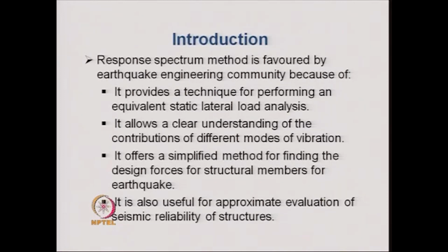In the design stage, it is better to have an equivalent static analysis, so that the earthquake forces can be combined with other static loads, or the responses produced due to other static loads, and a combined critical member force can be obtained, for which the member can be designed. So, this equivalent static lateral load analysis, which is performed in the response spectrum method of analysis, has become very attractive to earthquake engineers.